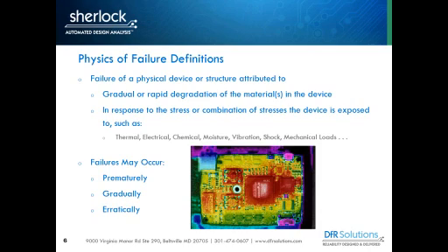If something fails in what you think is a random manner, it may not be random. It may be that you have such large defects that the stress levels in your joints are excessive and they're wearing out early. But it will look like a random type of failure.